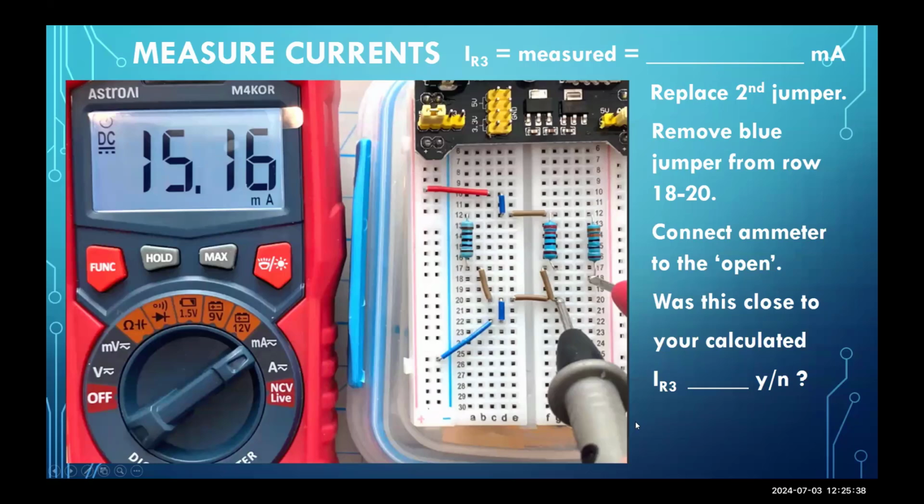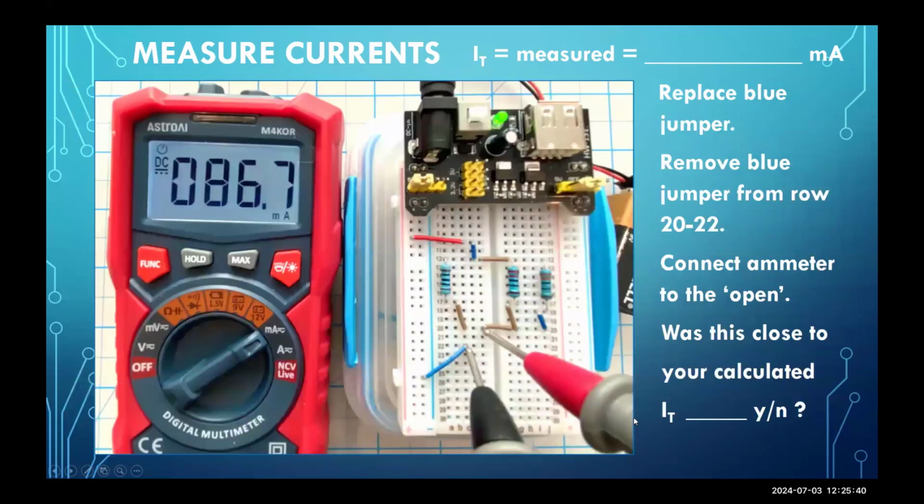Next, we're going to confirm total current, and I could do this in one of 2 places. I said, in order to measure total current, you do have to replace that blue jumper wire here. You've got to rebuild the current path for R3. I removed the blue jumper wire in the lower portion of the circuit, created an open here, and stuck in my ammeter probes. And yes, I'm getting something not far away from the 87 milliamps that we had calculated. I'm happy with the 86.7 milliamps.